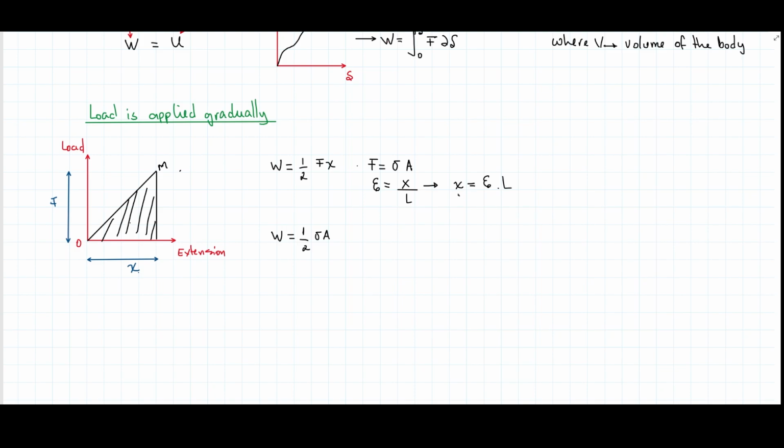But also, strain is related to stress by what? I know that strain equals stress divided by the Young modulus, because this comes from the proportionality curve that I showed before. So now if I factor this in here, then I could write that this is equal to sigma divided by E, Young modulus, times L. Then let me rearrange some terms, because this is going to end up being that work equals 1/2 of sigma squared divided by E, Young modulus, then times A and L.